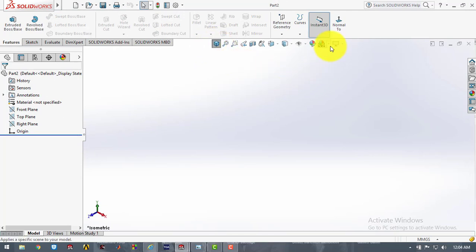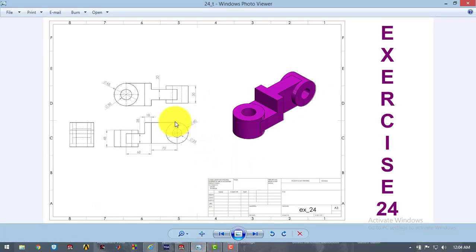Now first let us make the background plain white. Now from the dimensions, first we will create this L-shaped part. So here are the dimensions. This vertical line is equal to the diameter of the bigger circle, that is 60 mm, and this horizontal line is 68 mm.